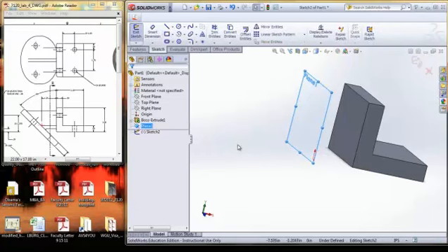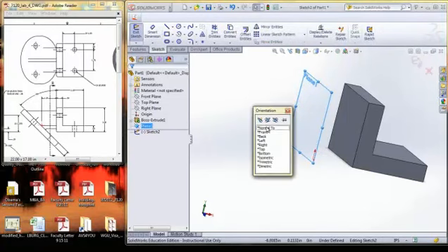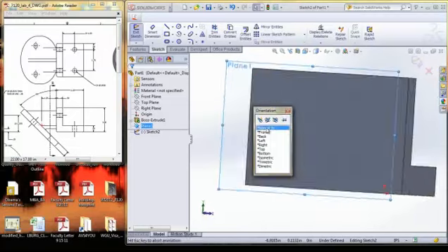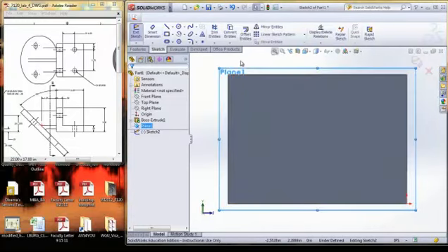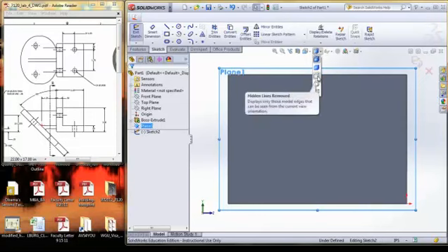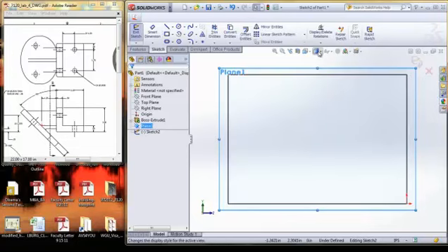Okay, then I'm going to go in there and create a new sketch, and it went straight to that plane. Then I'll hit the space bar and go normal to, so I'll double click normal to. And then I'll just go ahead and create the geometry. I want to change my display to, let's see, hidden line. No, not hidden line, removed. I want to see the hidden line. And I'm going to draw a line. Now this line can be a center line.